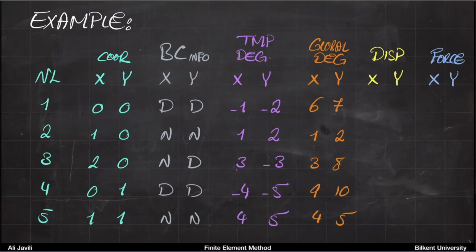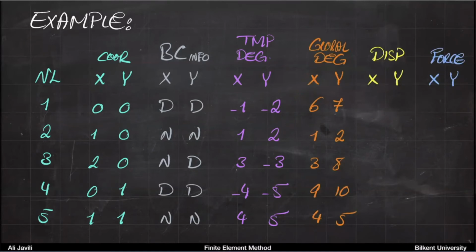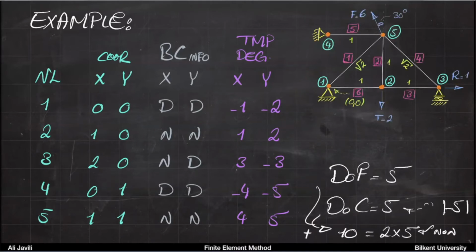So the displacements, I don't know if you can just remember the system. So let's go back and forth between the pictures a little. If you think about node 1, displacements are 0 in both directions. So 0, 0. At node 2, the displacements are unknown basically in both, but the force in the y direction is known.